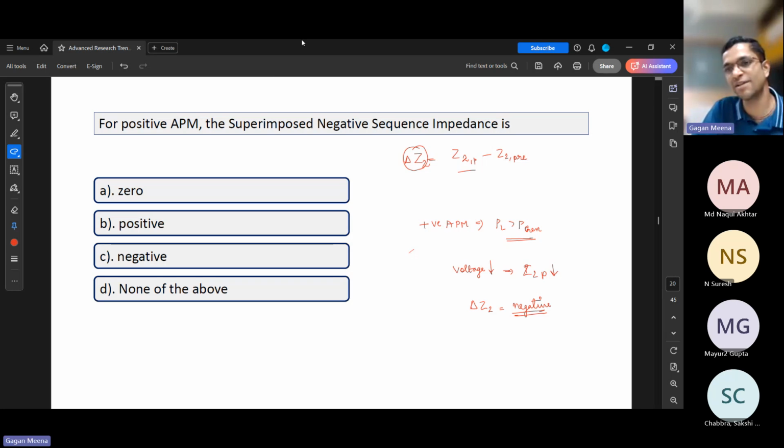We cannot decouple the two, and power is more related to voltage here. That's why we say we can decouple for a bus in distribution. Normally, all distribution stations have a capacitor bank, and they try to maintain a unity power factor. And say the active power somehow reduces and is not meeting the requirement, then the frequency will dip, right?